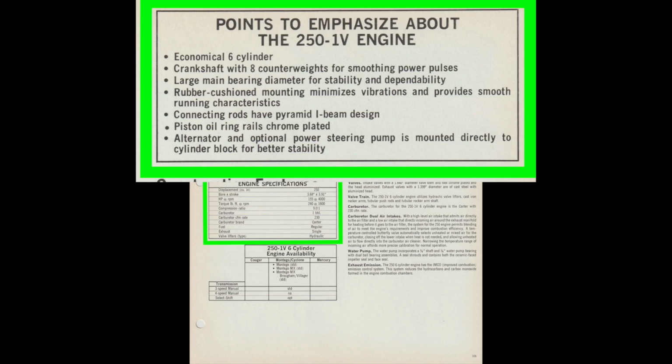Connecting rods have pyramid I-beam design. Piston oil ring rails, chrome plated. Alternator and optional power steering pump is mounted directly to cylinder block for better stability.